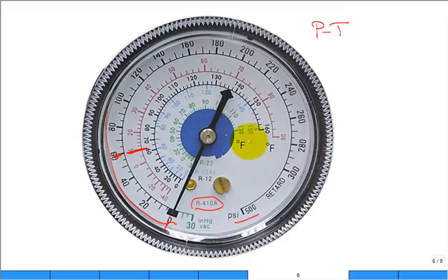Oh, degrees F right there, yeah. Then its temperature is 10. That's the saturation temperature. So the PT chart, which you thought was confined only to thermo books, no, it's in the technician's pockets. It's on the technician's gauges for the refrigerant 12, 134A, 22. Different refrigerant gauges have different labels on them.